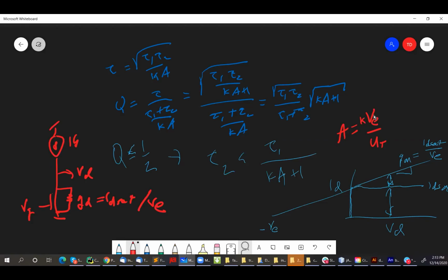Okay, so we should be able to simulate that, right? That's just a separate circuit that we can simulate. We can make a transient simulation of it, put a little tiny capacitor on here, any capacitor, and just do a time domain simulation. Sweep this voltage and look at this voltage. It should go down like that, right? As you cross the threshold. And so the result of that was, I'll show you.